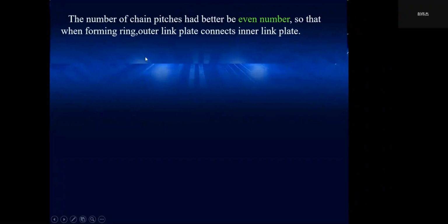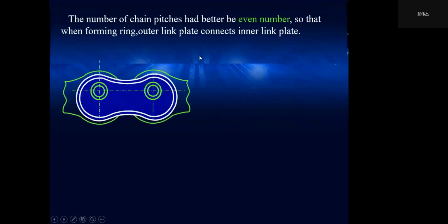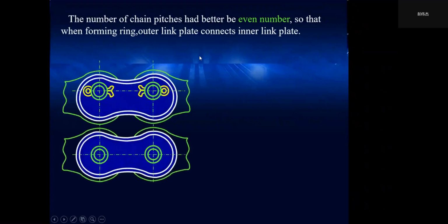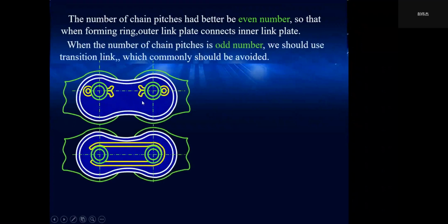And the number of chain pitches had better be an even number, so that when forming a ring, outer link plate connects inner link plate. Like this.